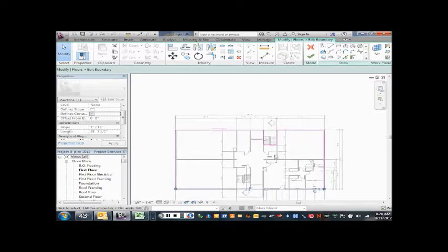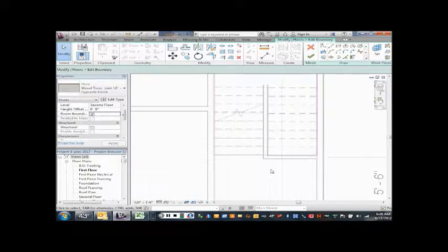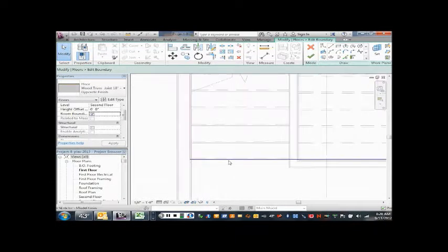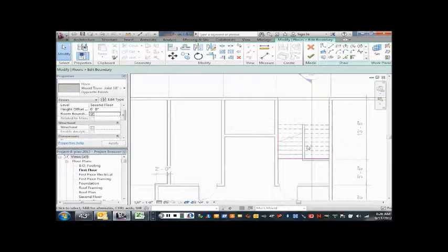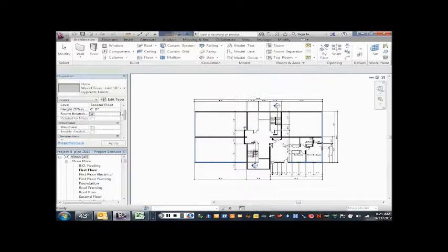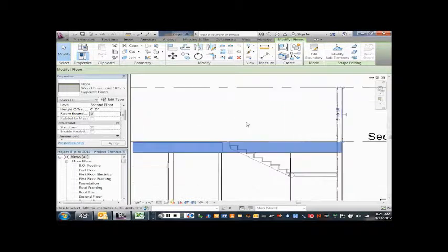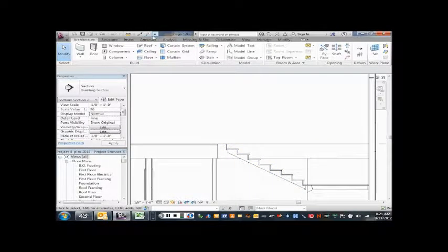But down here, I want it to end where the stairway ends at the upper level, right? So trying to figure out the stairway, I could say, okay, I put it in line with this one, or this wall here. Let's just see what happens. I'll finish that, and we'll see. Is that in the right location? I don't know. Okay, so I got that hole in there. If I click on my stairwell, this is the line of that hole now. We can see it. If I look at my building as an isometric, we should be able to see this hole. There it is, right?